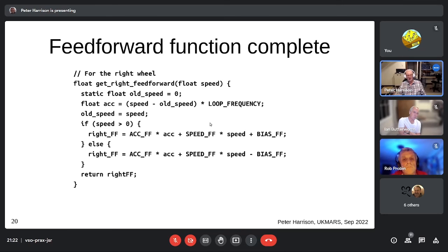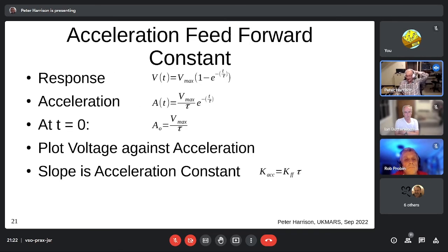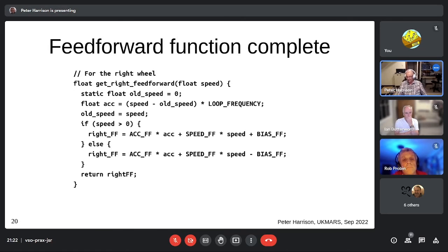So it's an extra voltage needed to drive current through the motor for acceleration and braking. So, Chris, that's the answer to your question from what feels like 3 weeks ago now, about why there is a step there. It's to drive that extra current in needed to do the acceleration. And this now is just a PID controller in case anybody asked, but they didn't, so you can forget that. Right, now I'm done. Unless anybody has any other questions.